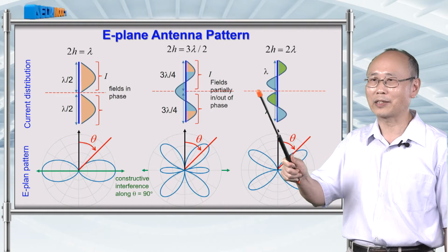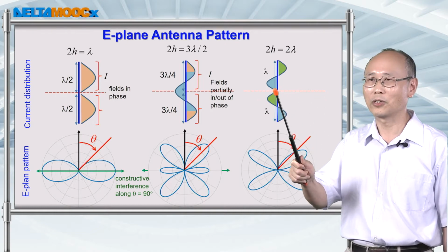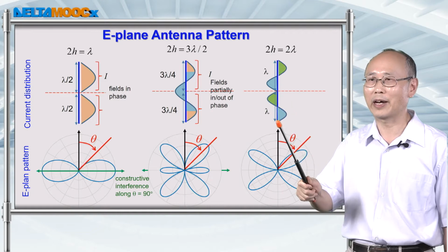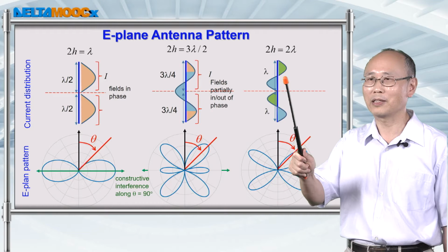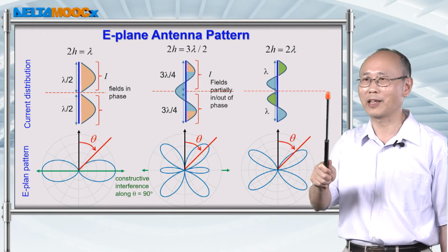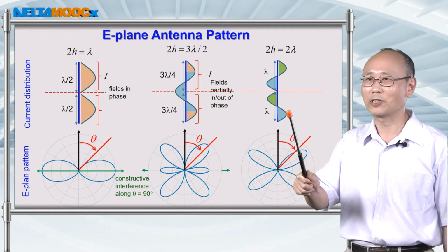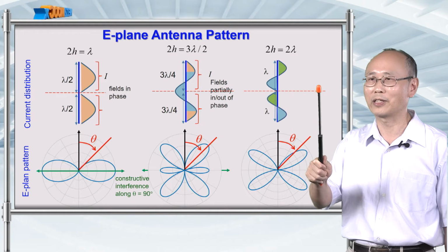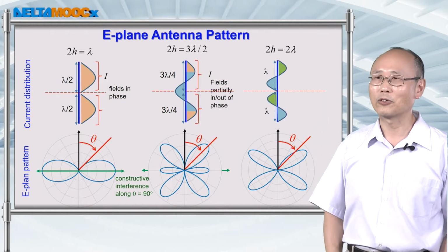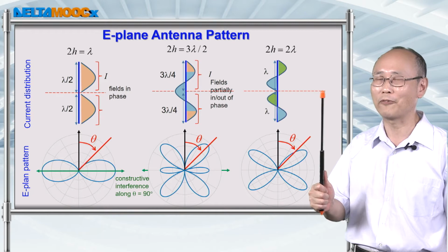Let's consider that in the far field along this direction, you can sort of divide this long antenna into 2 parts. And with the same distance from this antenna along this theta equal to 90-degree direction, just draw a line from this antenna and then draw another line from this antenna, and then you sum over the field to determine the total field in the far zone.